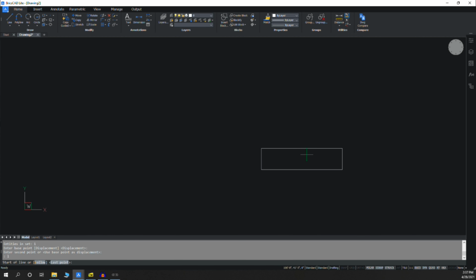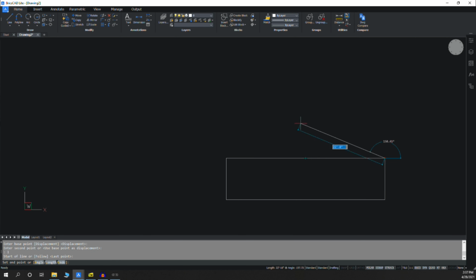So let's look at the elevation view real quick. In order to make a pitched roof, you can do it freehand, but we want a roof that's actually a pitch you can buy. The easiest way for me is to go off to the side and make a line that's 12 feet long. Let's say we want a 6-12 pitch, so I go vertical and make a 6-foot line. Now I've got a line that is exactly the right pitch for the roof I want.